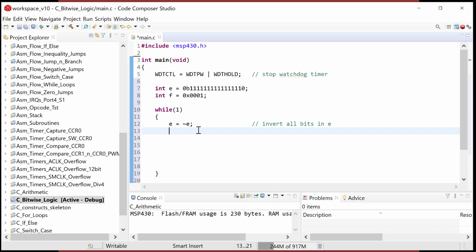And now what I want to do is set a bit using an OR operation. So watch this. I can go E gets assigned E bitwise OR with a mask. So bit 7, I mean, think about this. It could be 0B, 1, 2, 3, 4, 5, 6, 7, 8, and that would work. This is bit 0, 1, 2, 3, 4, 5, 6. Oh, it's bit 7. So boom, boom. So bit 7. So that mask would work.